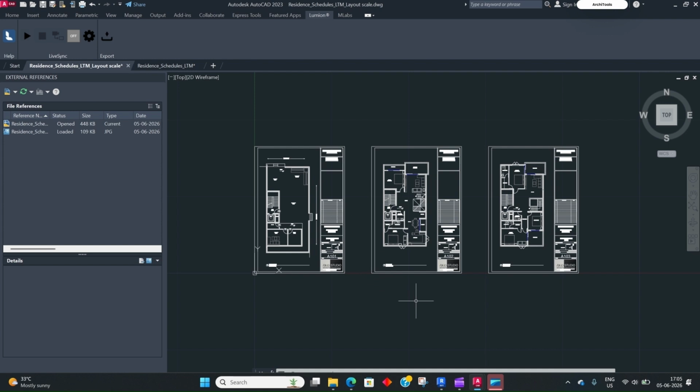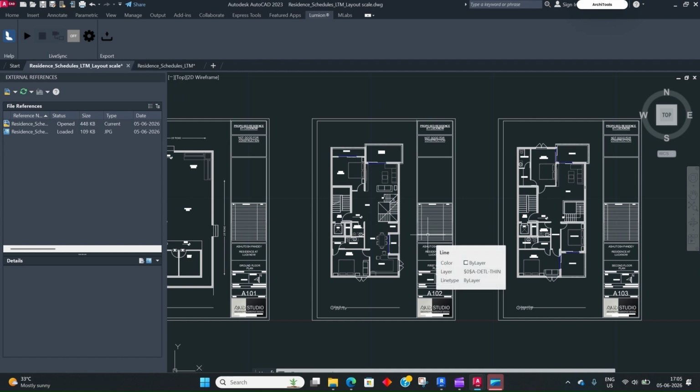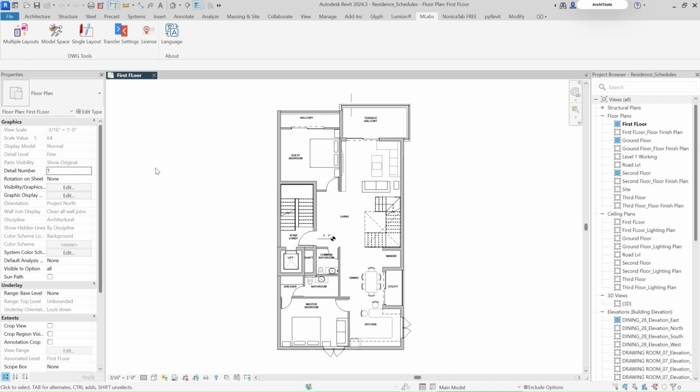I find that there is a limitation in this MLabs plugin to export your CAD drawings in a single CAD file. It's that if you have multiple views placed inside a single sheet and you export it in the layout format, there might be the chances that some of the elements inside that view might misbehave. Other than this, if you have one scaled view placed inside the sheet, this plugin is very helpful in getting your exports in a single CAD export.